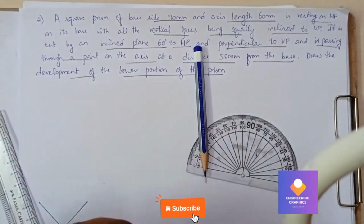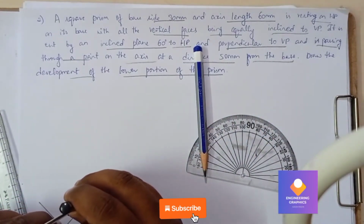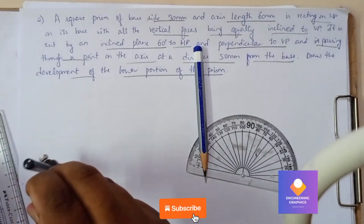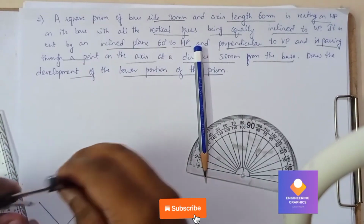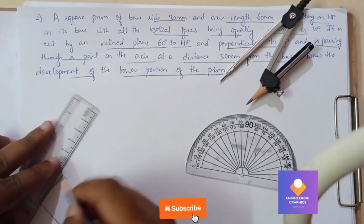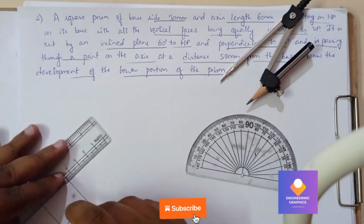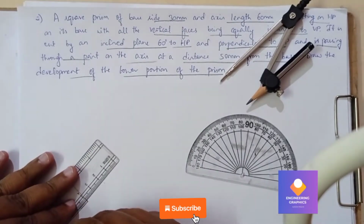Take the compass and cut an arc for 30 mm. You can measure it from any one of the edges, from the reference point. And then join it to get the square in corner position. You can show the dimension on one side, that is 30 mm.